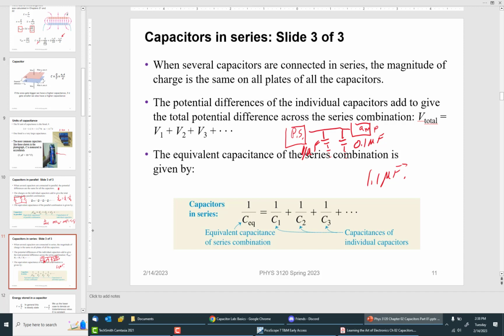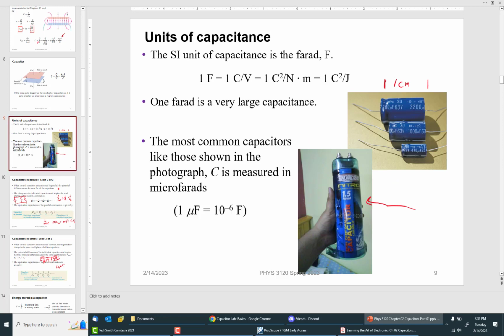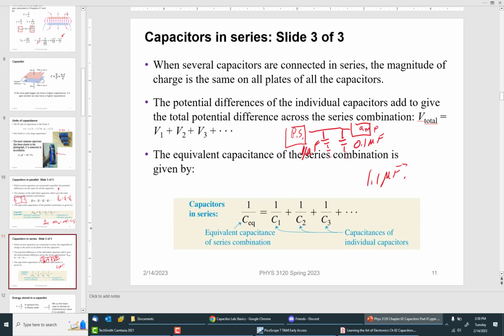Because it turns out in the real world, the 1 microfarad capacitor looks like this, because these work best at low frequency. And the 0.1 microfarad was one of those little yellow guys we use. They work better at high frequencies. So that's why you needed 2 separate ones. And what those did, they took away the ripple. Remember when in the oscilloscope lab we were looking for ripple on the power supply? And they get rid of it by capacitors. In fact, in chapter 3 we're going to create a power supply, and we're going to examine that ripple and how the capacitor deals with it.